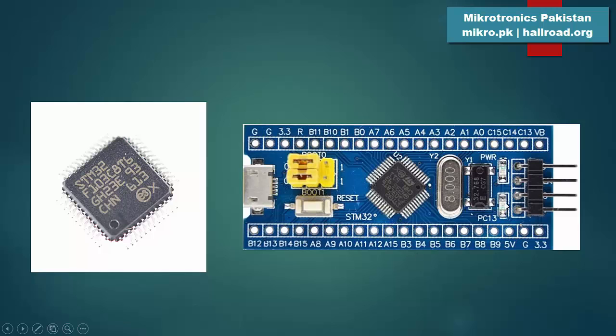There is also one LED attached on this board, which is connected to the PC13 pin of the microcontroller, so that you can make a quick program to test this LED as on or off. And here is the power supply LED.